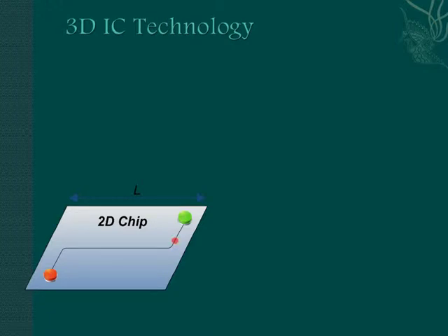3D technology has become one of the most promising methods in today's integrated circuit design and manufacturing. With 3D, we can divide the chip into several layers and connect them together. Obviously, the yield of a single chip can increase and the interconnection latency can be largely decreased. Moreover, 3D provides a new way to realize heterogeneous systems, break the memory wall, and increase the possible pin number.